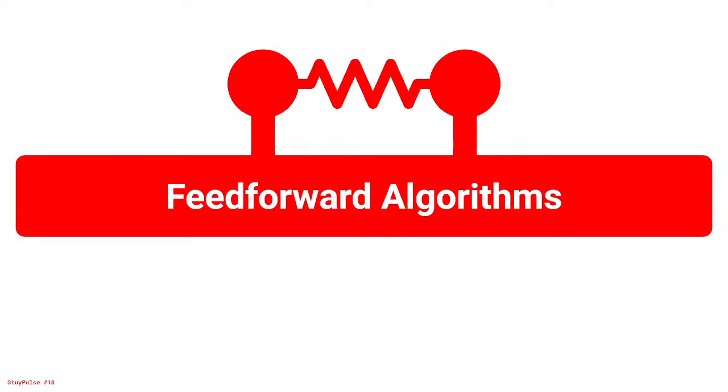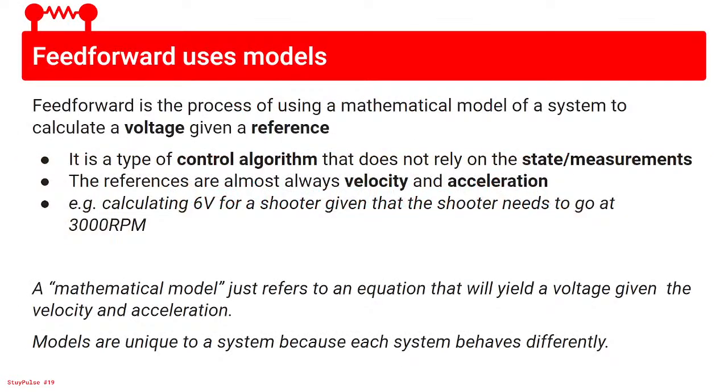No. Okay, cool. So feed forward, first algorithm. The goal of feed forward is to use a mathematical model of a system to calculate a voltage given a reference, right? So this is a control algorithm. Even though it doesn't rely on the measurement from a sensor, it's still a control algorithm, or at least the way we think of it, it is. The references are basically always velocity and acceleration.